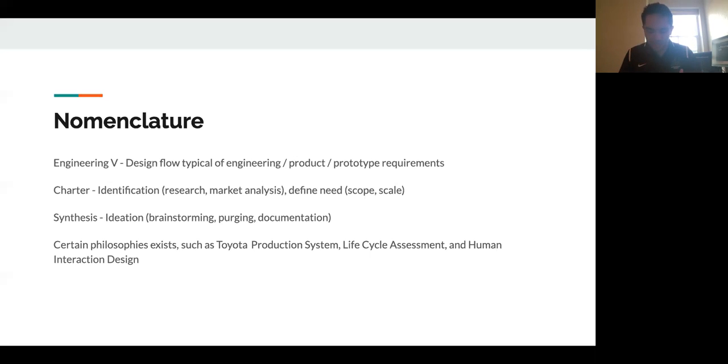What that means is that at every step within the manufacturing process, time and production are focused on providing what's necessary, specifically at that step and point in time, and that's repeated. So if I have this product from the start line to the end line, at step 1, I want to make sure components A through C arrive just as step 1 starts. And when step 1 is about to finish, step 2 is already getting its parts D through F ready, so that when the product arrives at the next step, D, E, and F can be installed on that product. And essentially, we have just-in-time manufacturing occurring for that product in a specific step. It's a just-in-time philosophy.